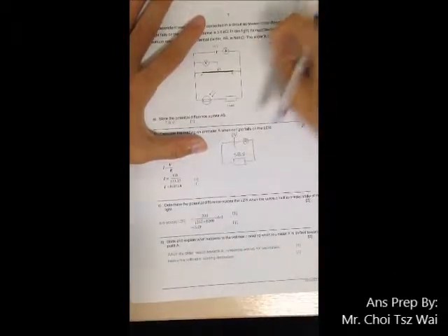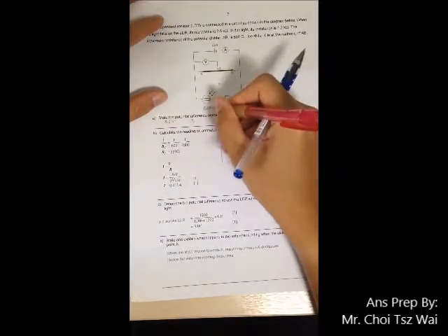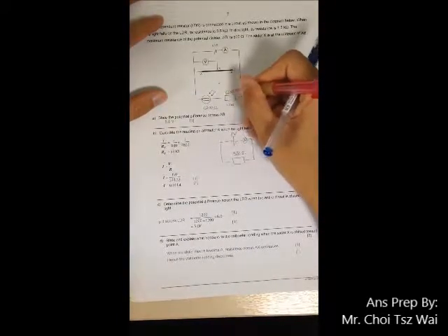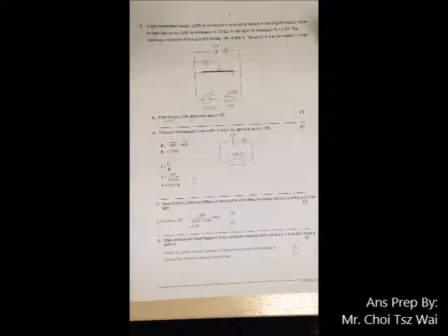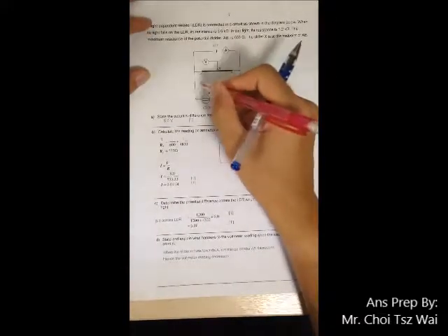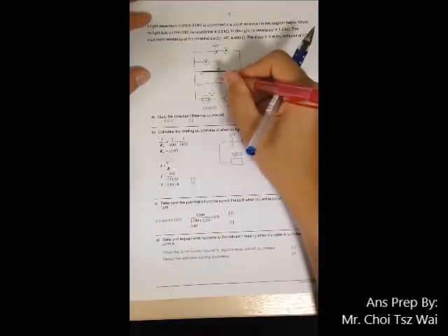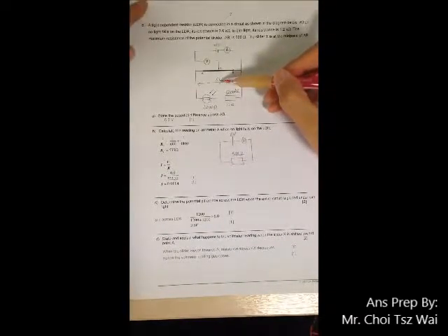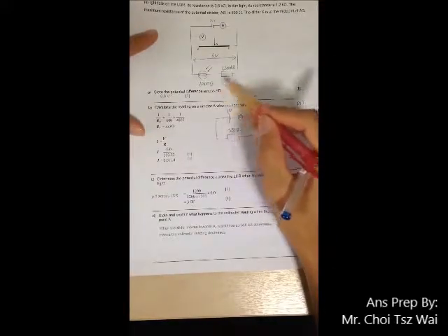When the circuit is in dim light, the resistance of the LDR will change to 1200 ohm. Conveniently for us, the fixed resistor also has 1.2 kilo ohm. It's very simple. You know that the potential difference between these two components is 6 volt, and because they have the same resistance, this potential difference is going to be shared equally between the two components. So just take your 6 volt, divide by 2, and you will get 3 volt, because these two have the same resistance.